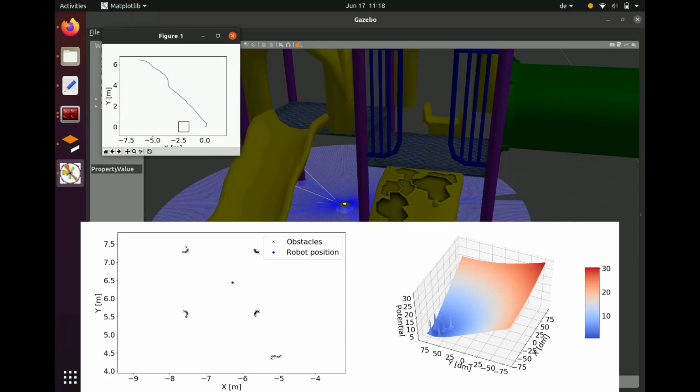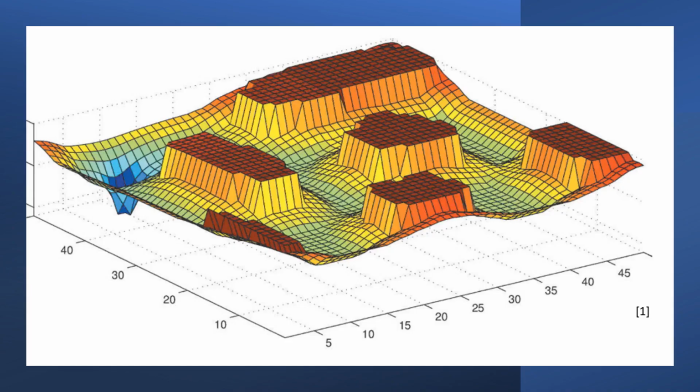With some more work, we could create a permanent potential field that consists of all the obstacles on the path and gradually build up a map-like potential field for global path planning, like in this graphic from the book. Moreover, we could add some damping to prevent the robot from oscillating. Furthermore, we could adjust the goal potential field to have a quadratic shape near the goal and map the forward velocity to the created force, to make the approach towards the goal smoother.